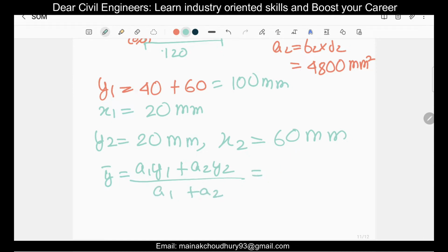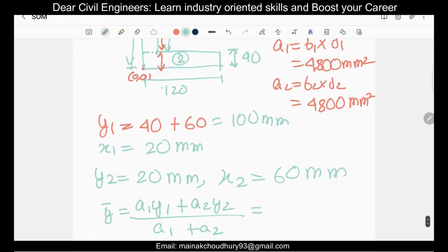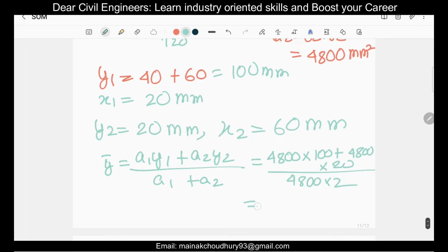So if you put all this together: 4800 mm square into y1, that is 100, plus a2, that is 4800 mm square, into your y2, that is 20, and divided by a1 plus a2. This unit will be mm cube and the bottom will be mm square. A1 plus a2 is basically 4800 into 2, right? So the answer will be in mm, and the answer will be 60 mm.